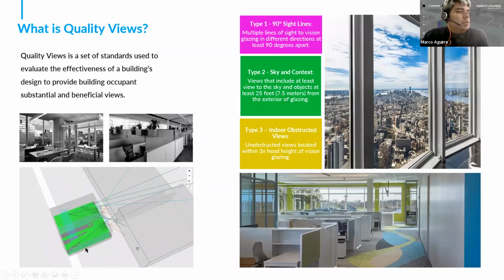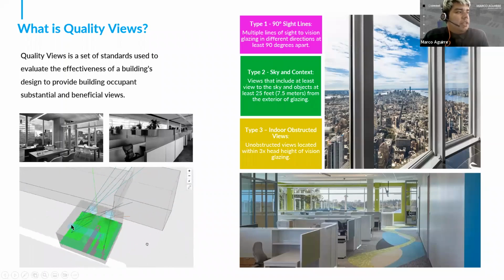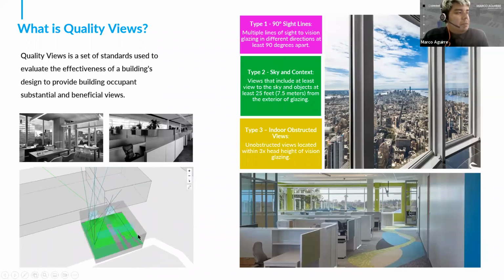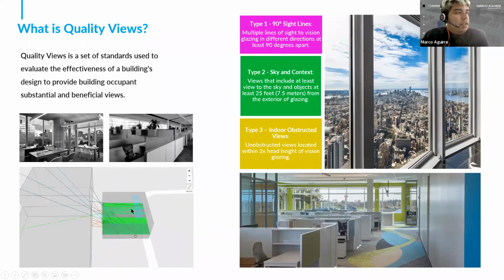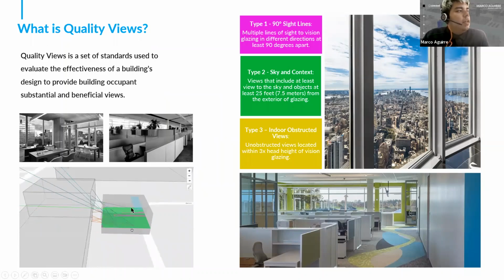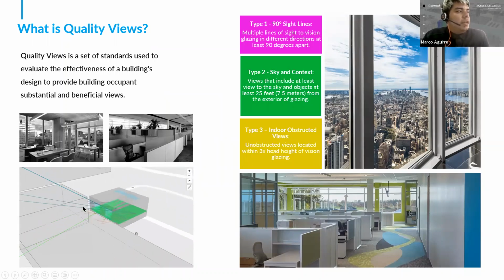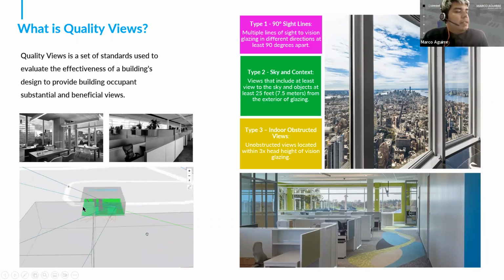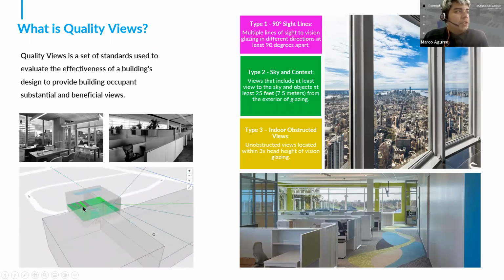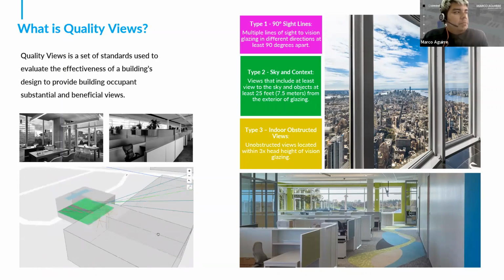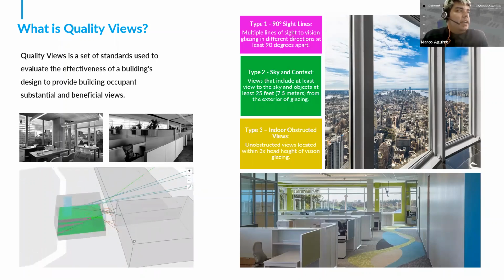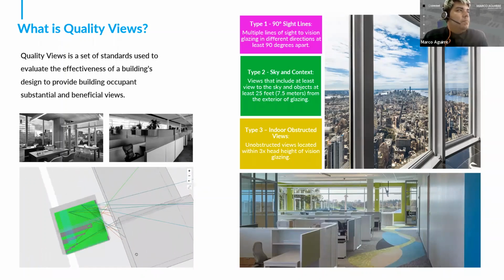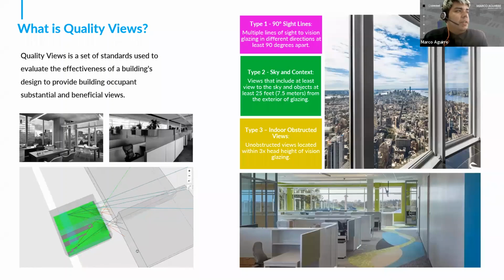How this analysis works, you can see here, is another ray tracing method, but this time it's casting a ray from every grid point within the floor plan and looking for any glazing objects. Once it finds a glazing object, it starts to measure: am I encountering any obstructions? Can I extend all the way to the sky? Do I have any obstruction before I can reach any window?